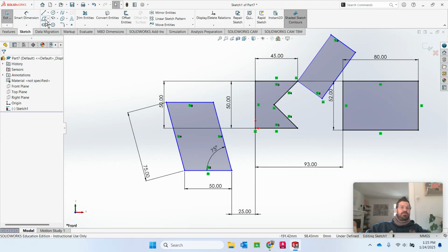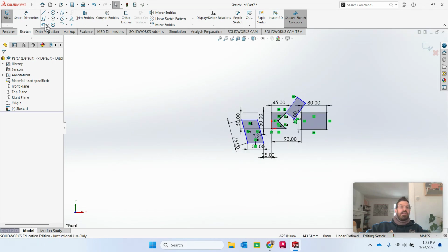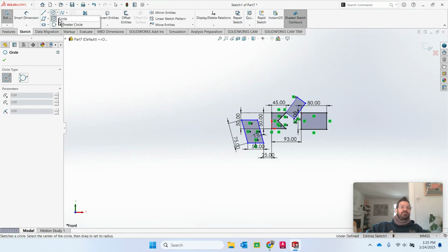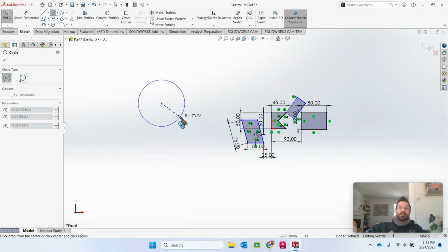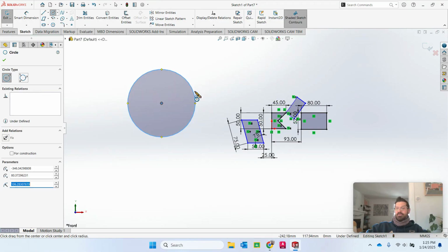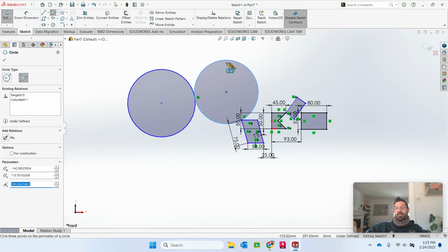Those are your rectangle tools. I'm going to just kind of get rid of some of this. Actually, maybe I'll just zoom out a little bit. All right. Circle works very similarly to AutoCAD circle. You click, you find a starting point, click, stretch it out, and then you can dimension it, right? 3-point circles are similar. Perimeter circles, so it's like I know one corner is here, one corner is here, and one corner is going to be somewhere up here, right?